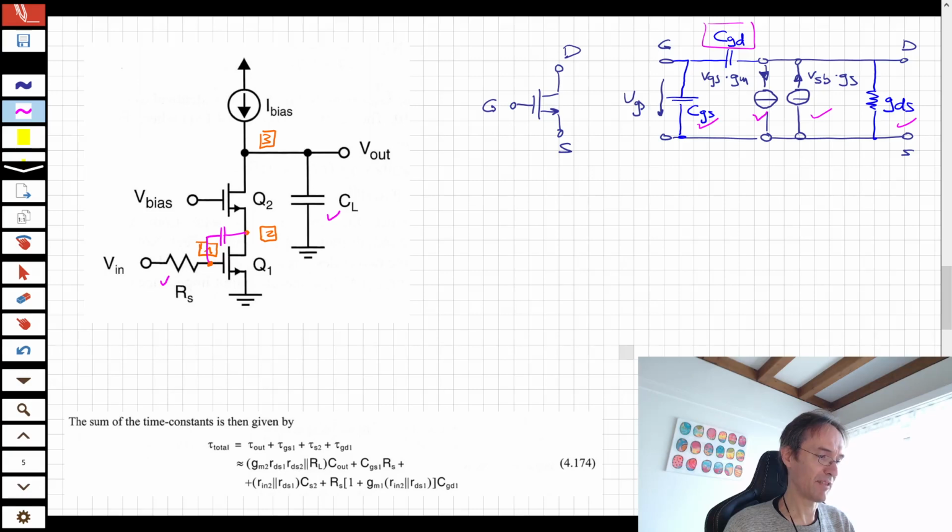So I make a simplified version of my transfer function. This is tsimp. I factored it out, and then I make a simplified version of my transfer function here by also substituting my driving point admittance and just setting all of the gate drain capacitors to 0.